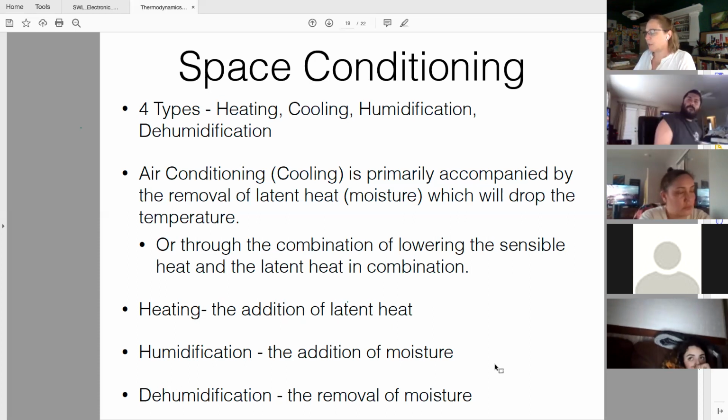There's a bunch of different systems that do it. What I was talking about was radiant cooling, running cool water through the floor that will act as a heat sink and take heat out of the air, but does not do the dehumidification.